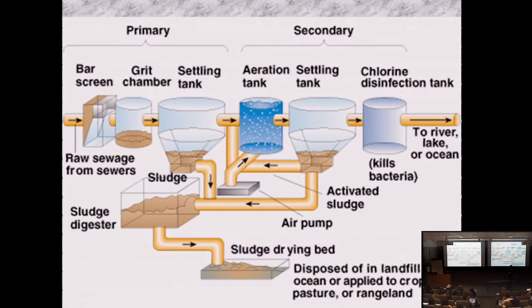If you're in a really landlocked area, you would drill a groundwater well and discharge it into the subsurface, because you don't want huge amounts of water just pouring over the surface. The sludge, remember we talked about how in Massachusetts it is not legal to use this on agricultural land, right? It's a valuable nutrient. It's not legal to use this in agricultural land unless you're feeding the products of that agriculture to animals. So what we do in Boston is we take that sludge and we put it onto rail cars. We ship it down to Florida and put it on the oranges down there. So that's how your orange juice is fertilized, from the waste, in part at least, from Deer Island.